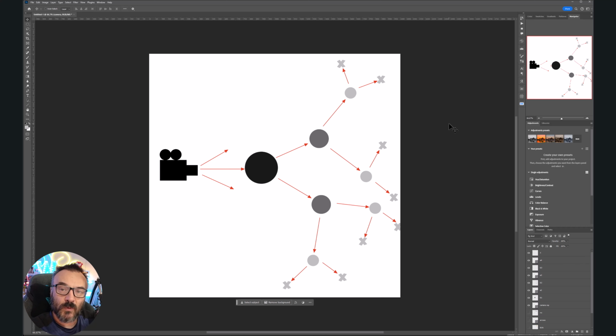Sometimes if you have worked with Vue before, you may have noticed how some objects look nice but certainly have these black or gray dots, depending on materials, and it can appear a little different, including with reflections. And what's happening here is that when it's calculating how many times it needs to go, it has this cut off line at that point. It says, okay, it's enough, don't render more. We can fix this. We can increase how many times it renders.